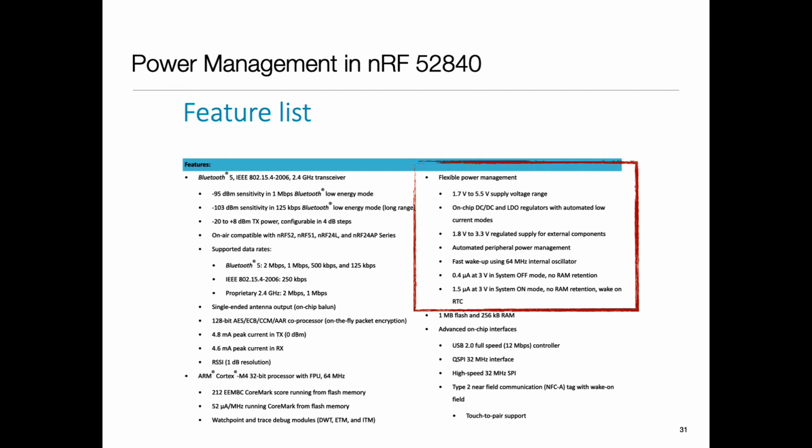Memories that you can put into a low power mode, and then they can last for a long time. And then when you start, you increase the voltage, and they can immediately come up. So the memories in your system have these low power modes, and also a combination went into optimizing this startup power so that you can make shutting down efficient. Likewise, changing clock frequency and changing voltage suffered from the same issues.